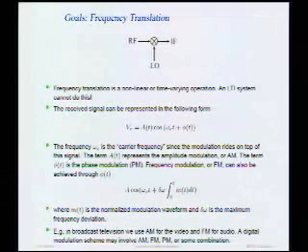100-something thousand kilometers. You can do math faster than I can, but basically it's simple. Lambda f is equal to c, where c is the speed of light. And so your antenna needs to be on the order of the size of the wavelength. So if you go to really low frequencies, the wavelength is huge. It's hundreds of thousands of kilometers at kilohertz. You can verify that. And so you have to build an antenna that's basically bigger than the Earth. Not a very practical situation.